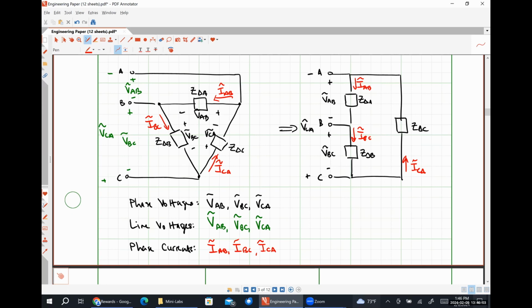One thing that we're going to see, particularly when we get to 3-phase power factor correction, is that 99% of the time you're going to opt to install your capacitor bank in a delta configuration. The reason for that is because your capacitor bank is going to use smaller capacitors in a delta configuration than it would for the same capacitors in a Y configuration.